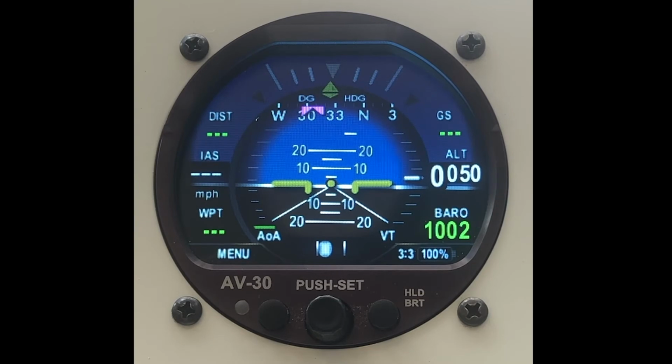available to you, in itself it has a GPS to derive the attitude and to do the computation for the DG heading. If you want to navigate from it, then you need to connect a separate GPS navigator. If it has a NMEA output, then that's perfect, and you just string the two together. There's one of the input pins on the D-sub connector on the back of the AV30 that will go to that external navigator, and then all the data is available to you here on this screen.